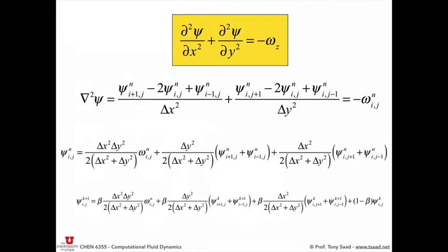Yeah, so here I was more thorough, saying this is c^(k+1) and c^k, because c^k, for point i minus 1, you already solved for that. But for point i plus 1, you haven't solved for it yet. In terms of implementation, you don't worry about the iteration index. You just use the same array. Okay? You just take the same array and just use it on the fly. You don't make a copy of it. That's it. That's our first recipe for a CFD solver.